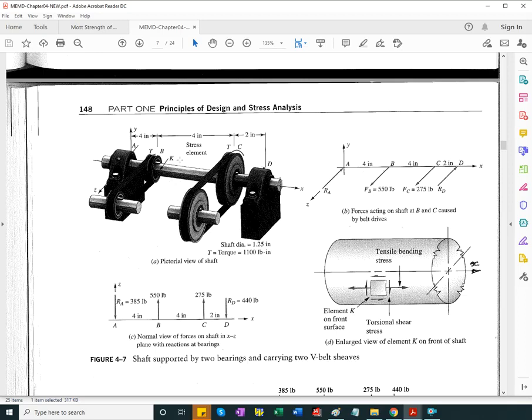This is a rotating shaft, and you'll see next chapter this is a fatigue analysis problem. But thinking static loading, the areas of the shaft of interest would be on the inside, where the z-axis, or parallel to it, comes out of the shaft.